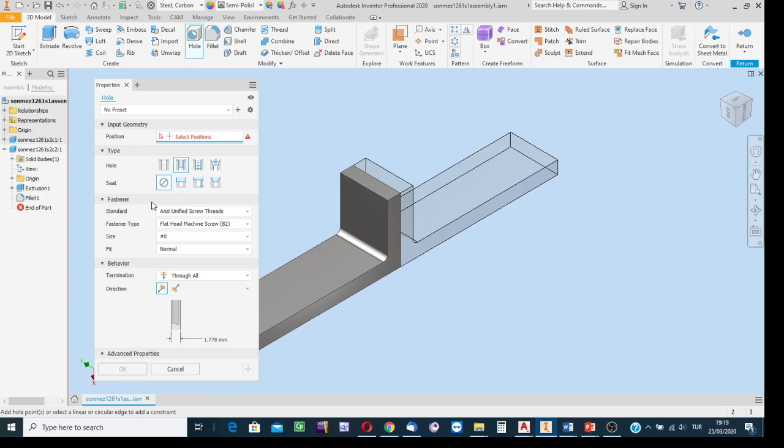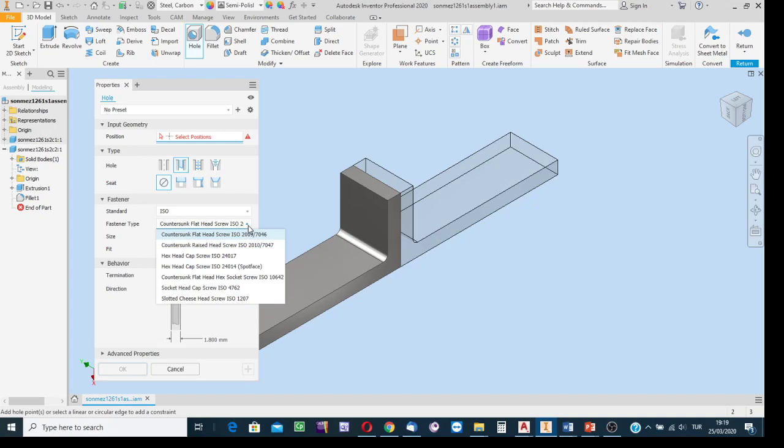Well, at fasteners part, select first the standard. You're going to use the fastener. It has been defined and manufactured in accordance with the definition of which association? Here is the question. And the answer, you know, unless otherwise mentioned, is ISO, International Standard. Select ISO option. Okay, and then from the other list, select the type of the bolt, which might be the case cap screw. Hexagonal head cap screw. In this example, the bolt will be hexagonal head type bolt.